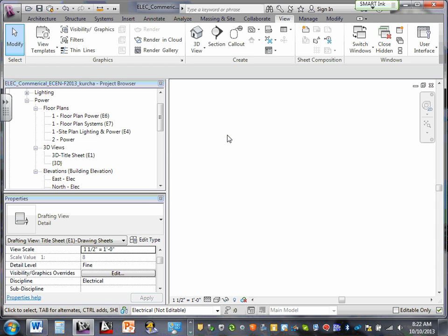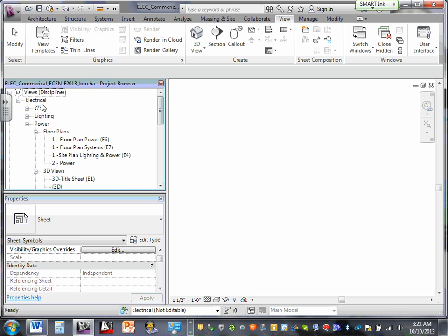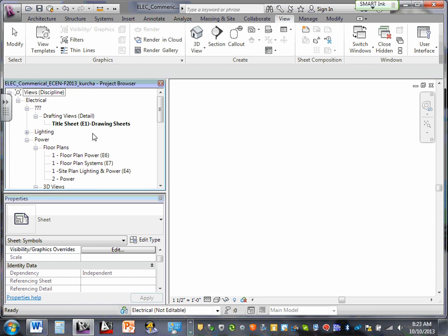Now, where did it go? Where is my drafting view? Where can I find it, right? Here's the draft. Now you can start drafting and writing and doing whatever you want to do with it. But before we do that, I'm going to go find it. Can you guys go here? Drafting view. Can you see where it sits? It sits under these question marks, drafting views, right there. So everything that you want to draft will be coming right under drafting view.